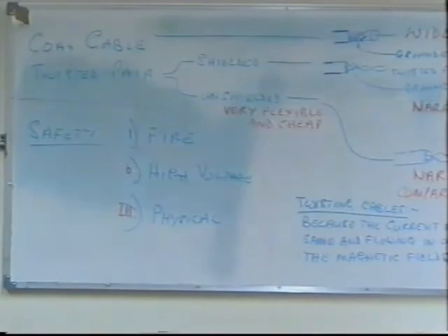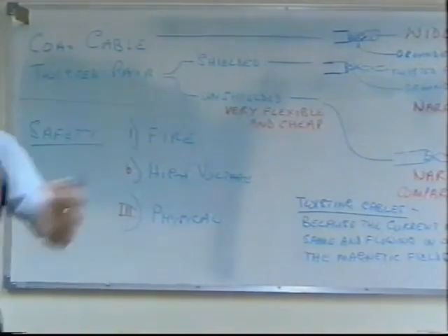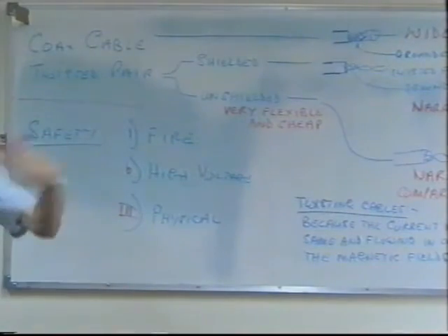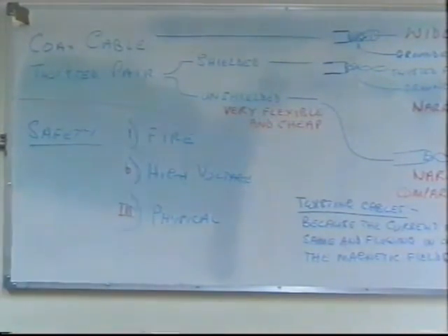And to measure voltages, instead of using the little probe of the meter, you use a long stick. Even then you can get a spark. There are different kinds of sticks. Some are used for 11 kV, some are used for 34 kV. So you can't use one for the other. You've got to be a bit careful, otherwise you'll burn the stick out.